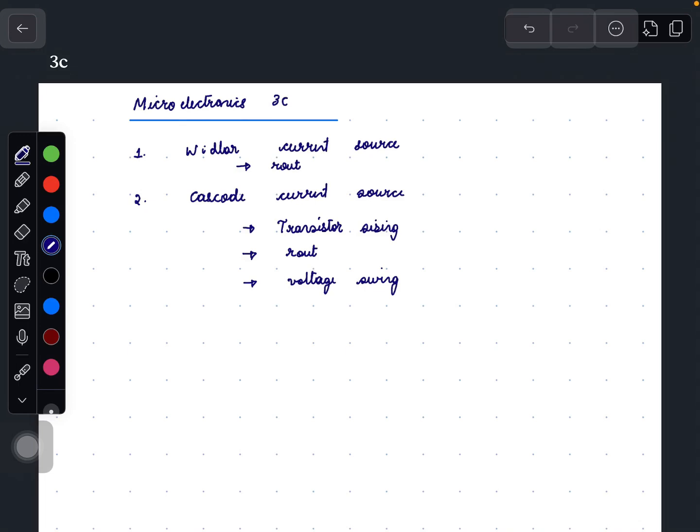In this video, I will talk about Widlar current source, how to find the output resistance of Widlar current source, Cascode current source, transistor sizing of Cascode current source, finding R out of Cascode current source, and the voltage swing of Cascode current source.